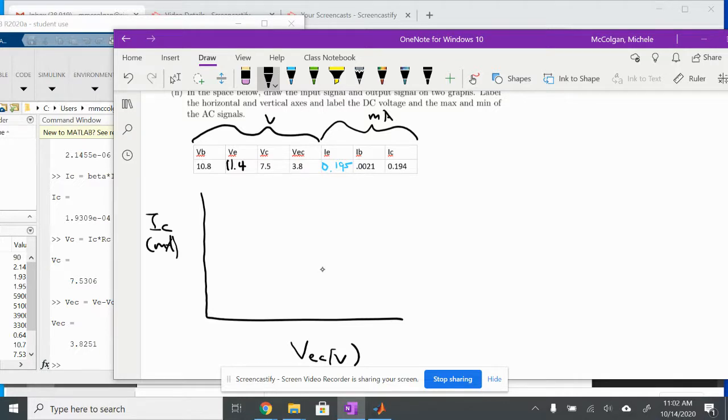And so those are the two cases that we put in our load line. If I do cutoff, that gives me my maximum VEC. So I'm going to have, this is RE, this is E, this is C, and this is 0. So this is RC. And if I were to measure the voltage at E, because there's no wire connecting E to C, I'm just going to get my V value here. So my VE is going to equal 12 volts.